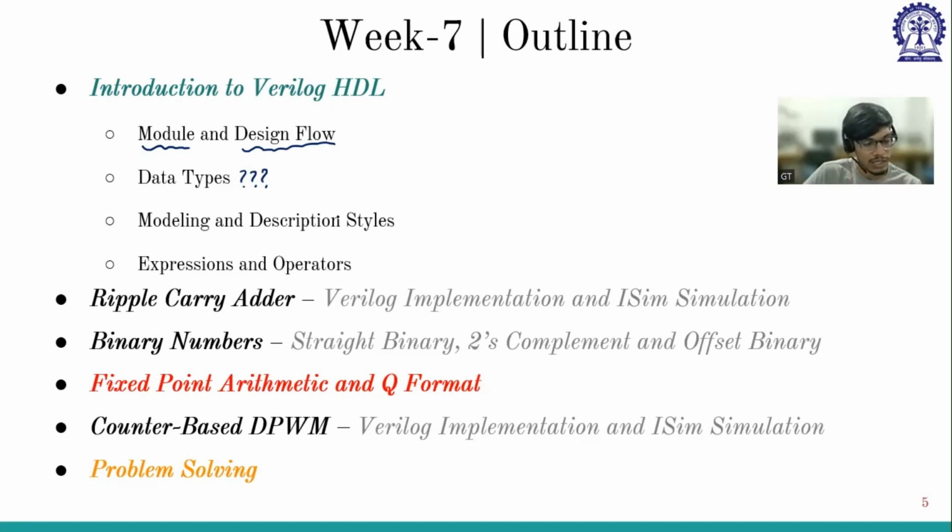And just like C, here also we have some expressions and operators. We will discuss what type of expressions are available and what type of operators we can use in the ripple carry adder, and then we'll move on to the Verilog implementation of the ripple carry adder. So here we will summarize basic Verilog coding, using which we'll move on to the ripple carry adder. This is again a 4-bit adder that Sir has discussed in the class. I'll quickly demonstrate the Verilog implementation, and then we'll move into ISim simulation, where I'll show the simulation of this adder.